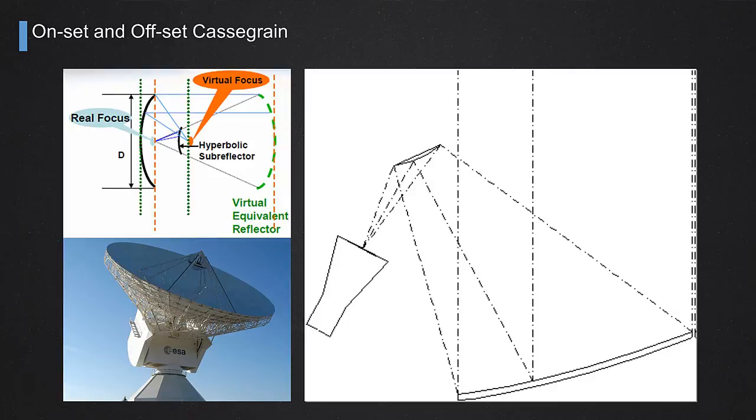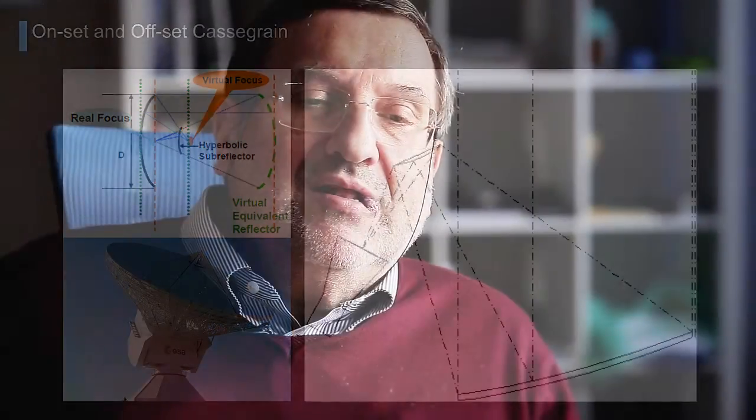The real focus, the physical focus, through the secondary reflector is put much closer to the antenna, so it allows a realization that is quite compact. You see that the double reflector configuration is equivalent, in fact, to a normal axial fed reflector with a feed that is far away from it. And again, this has got several advantages in terms of radiating performance.